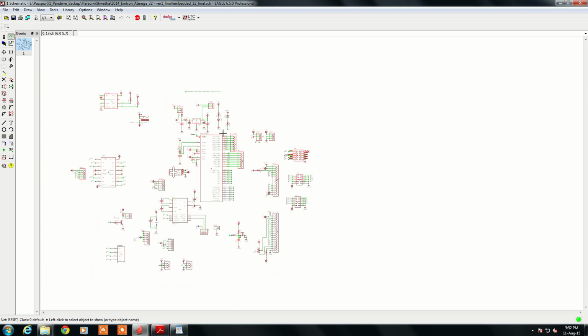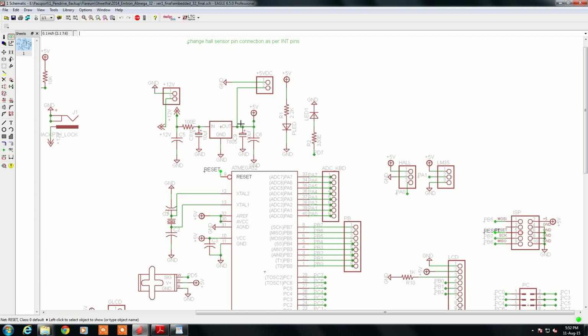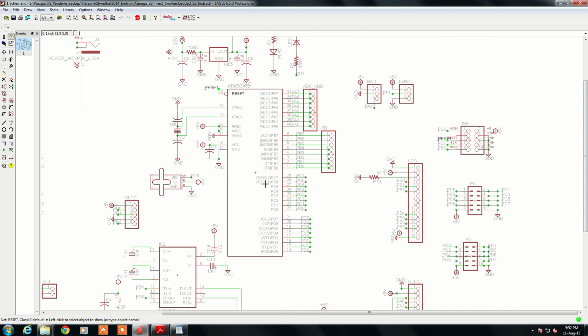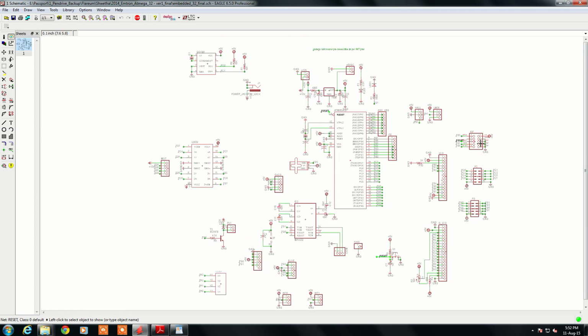So in short, now this board takes care of first the power supply design, so that if you connect a 9 volts or a 12 volts DC, the entire board will get the 5 volts after rectification. Then second, as far as the microcontroller is concerned, though we have connected LEDs, LCDs and some switches, still those signals we also brought to the connectors, so that as and when expandability is required, you can do that. Third is how to program this chip. There should be a provision called in-system programming, and nowadays this facility is available in almost all controllers. So without removing this chip, you can still program it by connecting a connector.